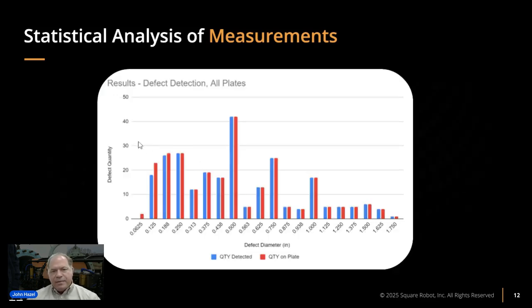The other piece of information that we looked at is really what's the other impact for ultrasonic testing? You've got remaining thickness, which we just showed that we've got a very high correlation across the expected thickness ranges there. The next component for us is the diameter. As we can see, the smaller the diameter, the more variability we run into.